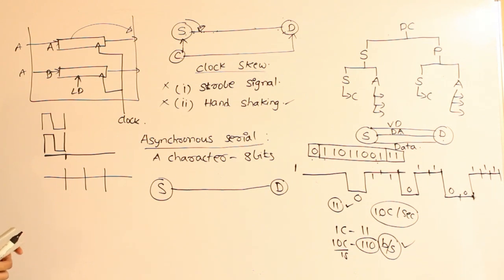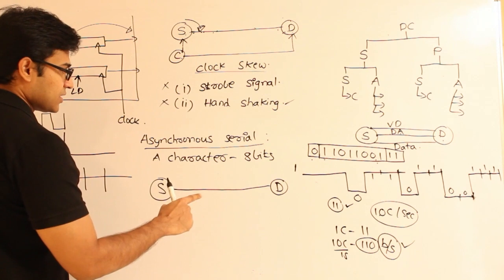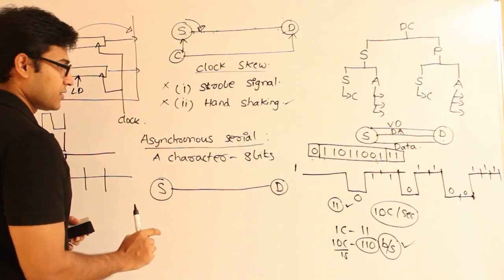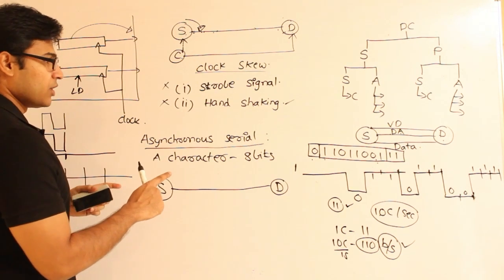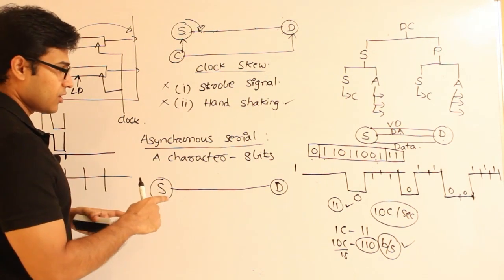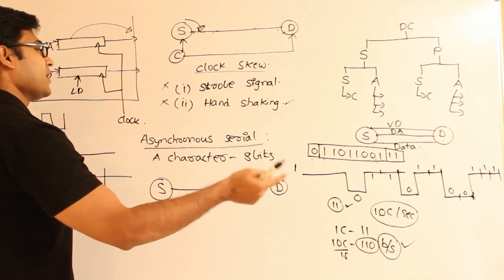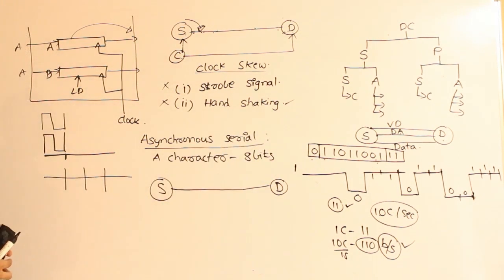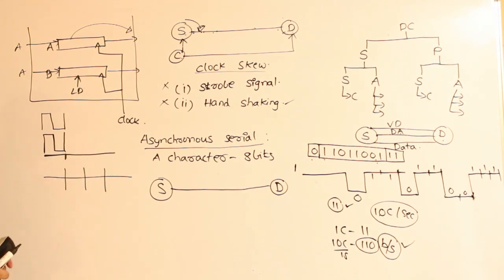So the main difference between synchronous and asynchronous transmission is, in synchronous transmission we are going to have a common clock. In asynchronous mode, we are going to have 2 different clocks, and somehow we have to again synchronize them, right? Both of them have to start generating the clock pulses at the same time, so that we can measure the bit durations exactly, right?